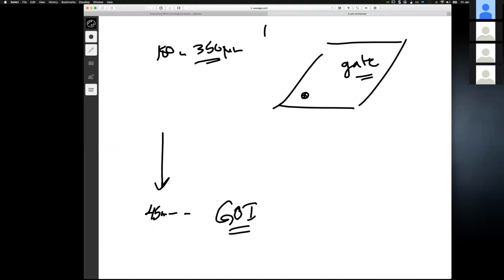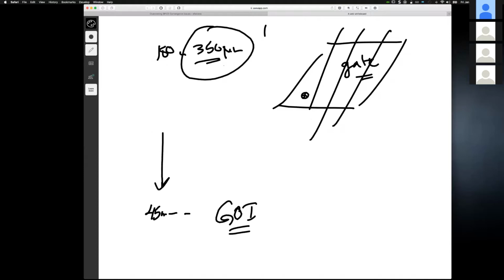Is there a design methodology? Maybe dividing the device. If it doesn't impact you through the parasitic effects, is adding more dividing transistors onto fingers a better thing or not? So you tend to make the design more robust by making judgments like these, if you don't know for sure that it's open-ended. But as Tim said, for a process like 350, no.